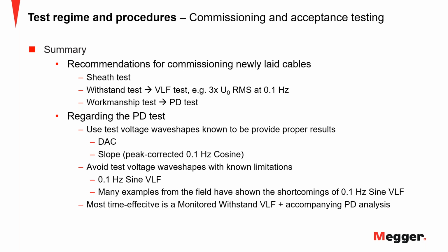Use a voltage that produces results comparable to power frequency, damped AC or cosine. Avoid sine wave for PD testing. And if you are under time pressure, or if you think that a VLF plus a PD test is too slow, or you want to do it in a different way, you can consider as an alternative a monitored withstand, where you do both at the same time.